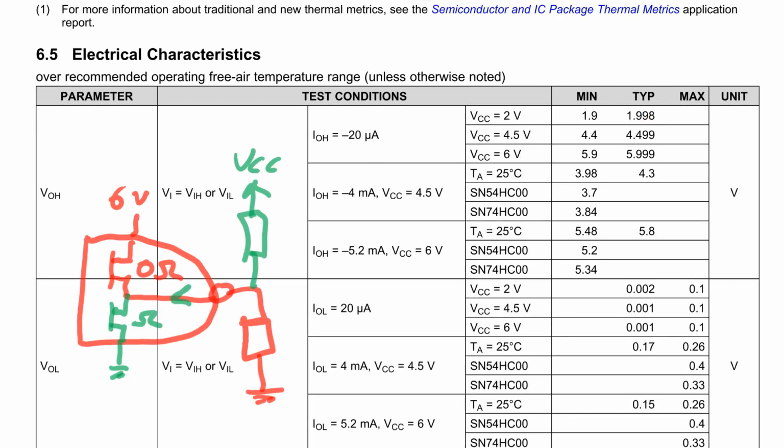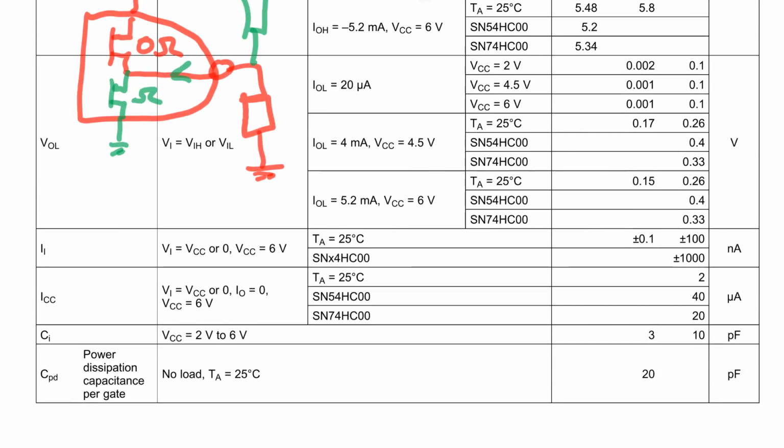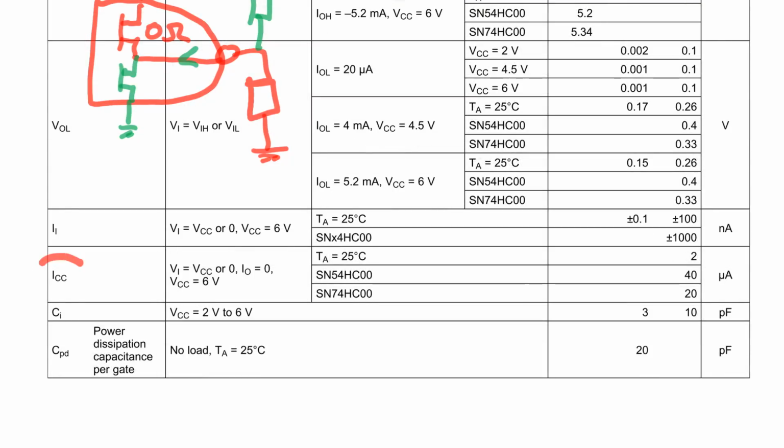These typical values, they might even say it here in the data sheet, I'll have to check, are not actually parametrically tested at the factory. They're just typical ones. They might batch test them occasionally to make sure that they're still meeting those typical values. But with the chip you buy, you can't go to them and say, I measured 1 nanoamp at 25 degrees C. They're going to come back and say, well, tough titties, it's plus or minus 100 nanoamps. That's all we guarantee. Your problem, not ours.